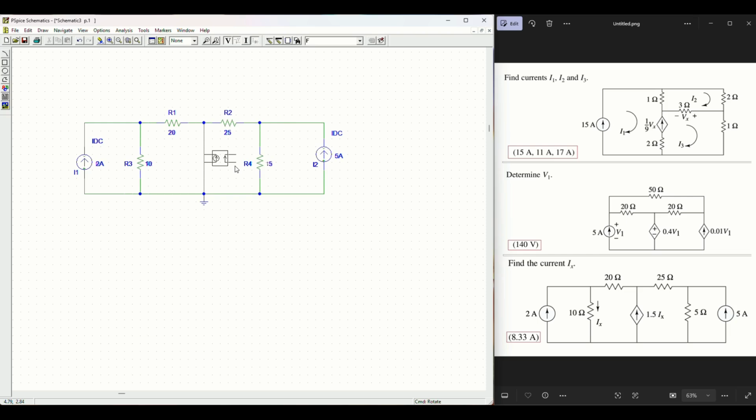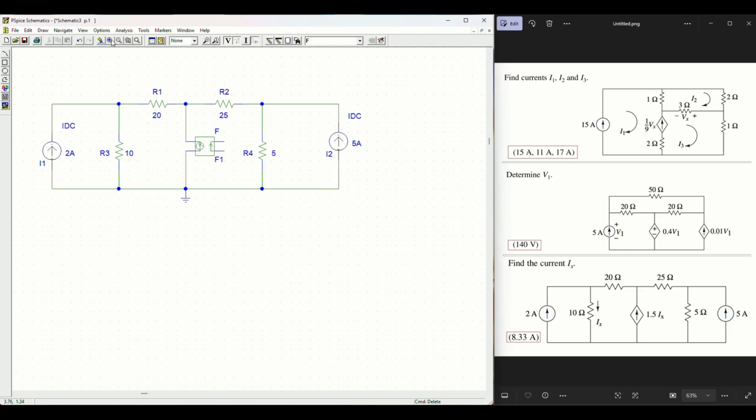So this is done. Now, in earlier cases, whatever we did till now contains all voltage dependent sources, so we were putting everything in parallel, right? But in this case we have to put this connection in series because we require current dependency now. So this should be in this branch. So let us first open circuit this one because we are putting it here. So let me put it like this.